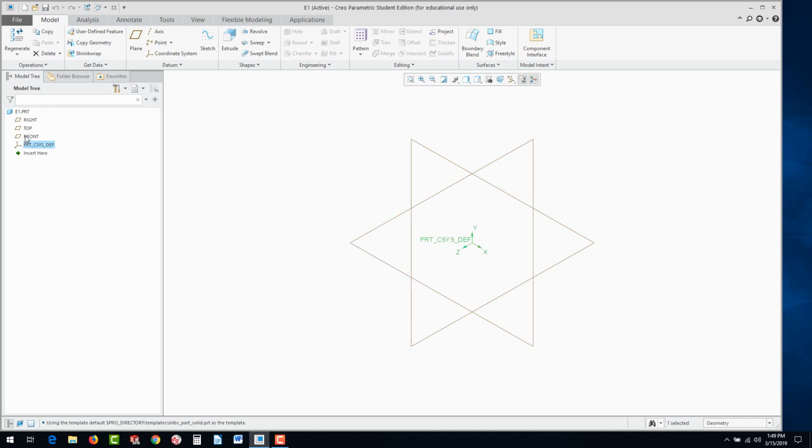What we're going to do is start our sketch on the front plane. So if you click on the front plane, there's a couple ways you could do this. You can do it by starting a sketch immediately, or if you know what feature you want, you could go ahead and select the feature, like Extrude or Revolve. In this case, we're going to start off showing you just this method, the Sketch option.